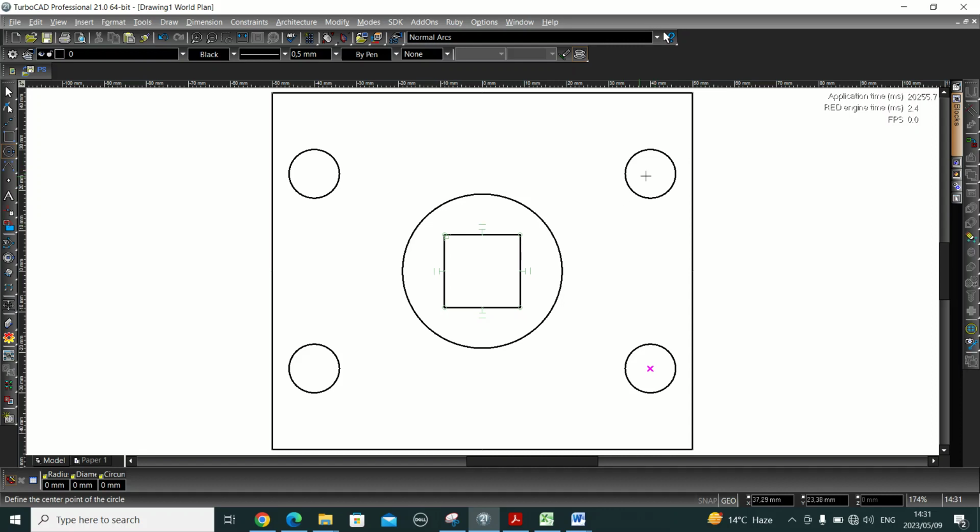All right, let's start with this one here. Go to the line tool, but now you have a rectangle. Click and hold there. Select this polygon here. All right, now press tab to define x. Since we're starting here, x is 40, y is 24. Press enter after that. You can see now you have your polygon there.